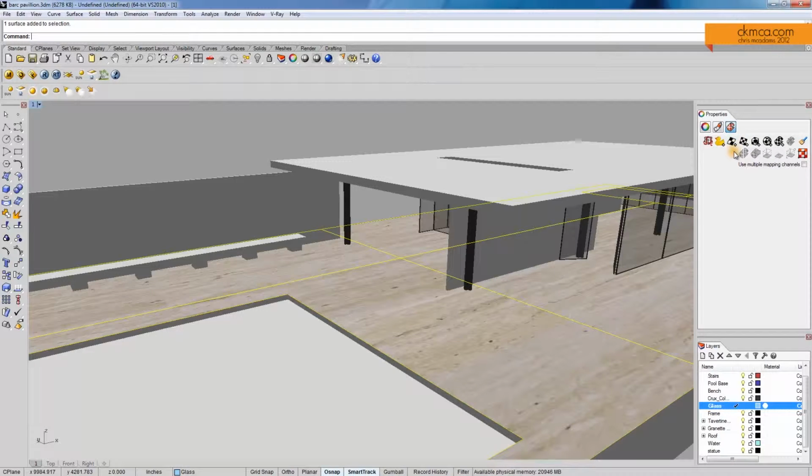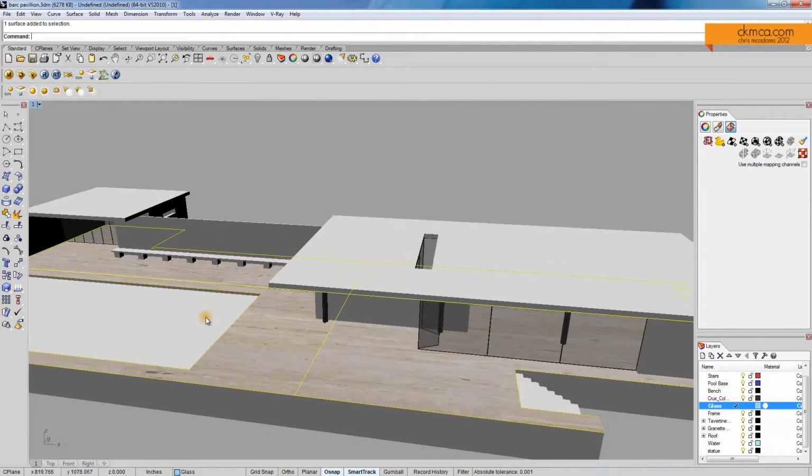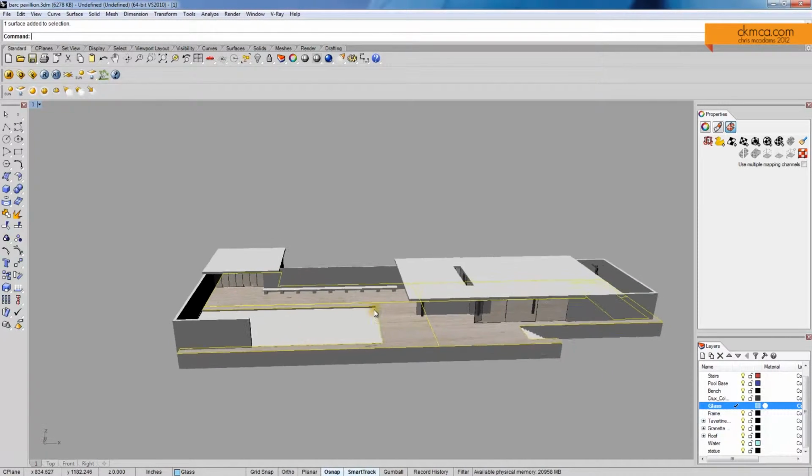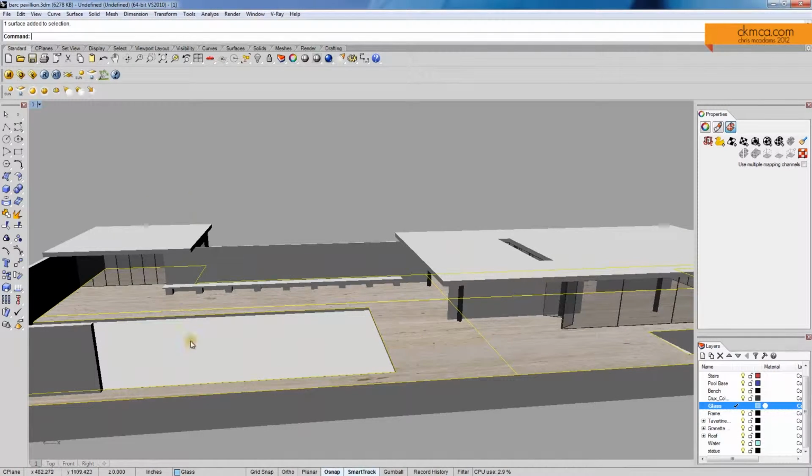Here is a surface. You can see it has a little bit of a wave, and what that'll do is it'll use the surface as a min and max. It'll have 0 on one side. It will call this point 0, 0, and this one 0, 1, and this one 1, 0, and this one 1, 1. And it will stretch everything to meet that. We want to have more control of that. If this surface was wavy, surface mapping might work well because it would actually map the material up and down the wave. For this, it's just a flat surface, and we can use planar mapping.